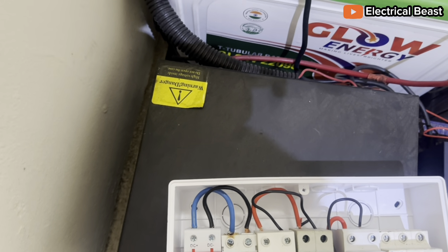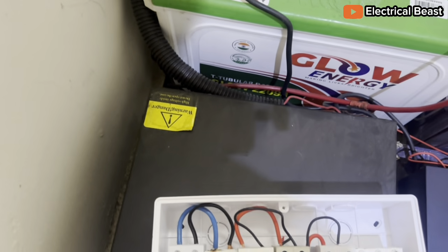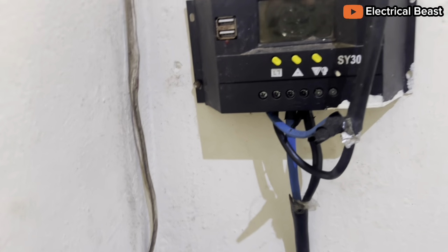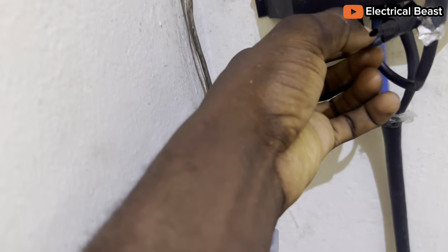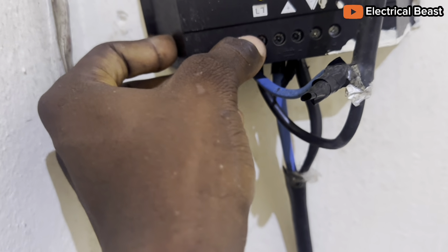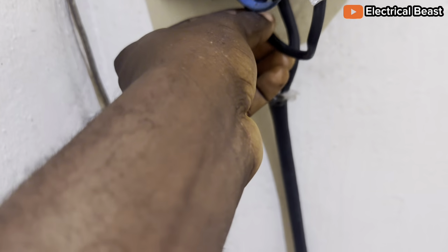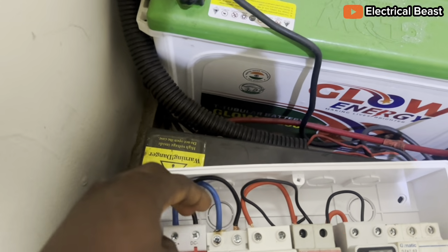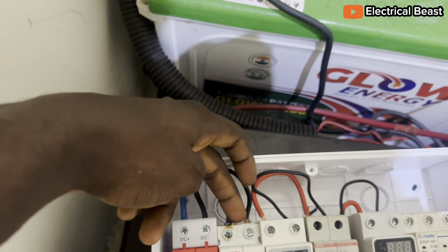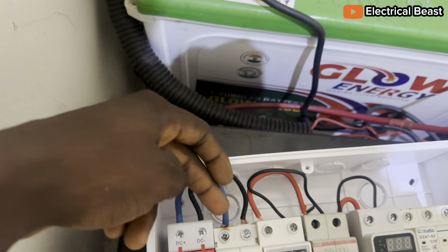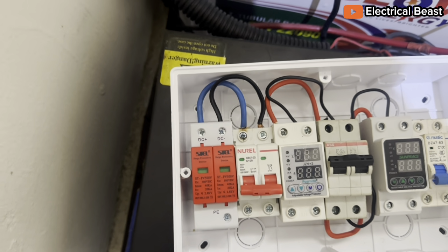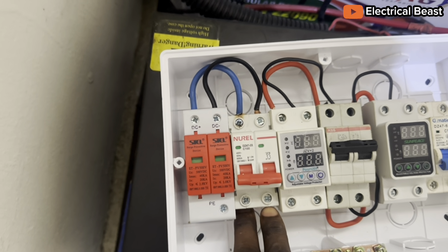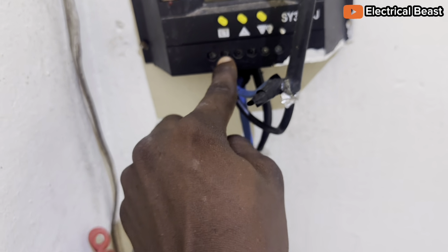This is a simple setup where you can apply this connection. Now you can see that this is the cable that is coming from the solar panels. It is directly connected to the panel input here. But normally it's supposed to come straight to the input of this. You loop it in positive and negative. When you loop it in here, it also loops to this surge protective device. Then the earthing is constant. Then the output here is what goes into this input here.